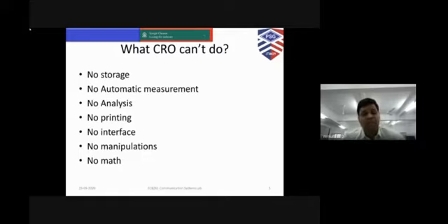For a good example, if you want to find the Fourier transform or view the spectrum of a signal, it is good to take a fast Fourier transform of the signal. Since the CRO doesn't support any mathematical operation, we will not be able to take the fast Fourier transform of a signal, or multiply, add, or do any math on the signal. We can see whatever signal is available at that moment, and it can be measured manually.